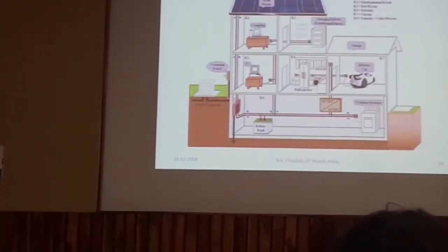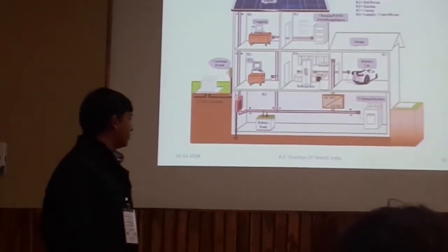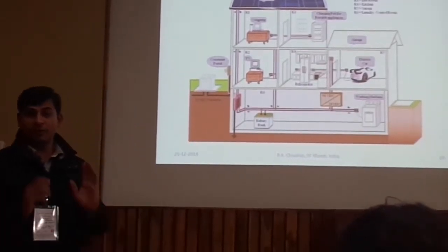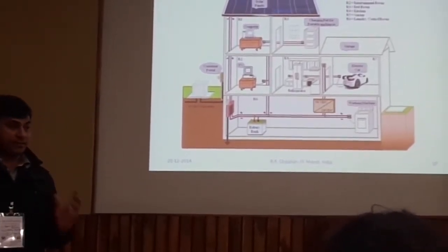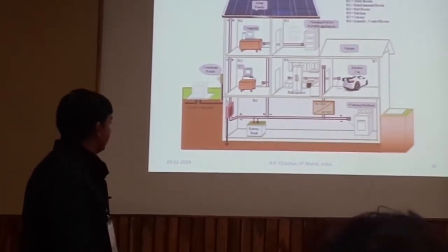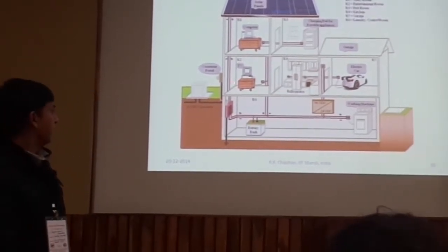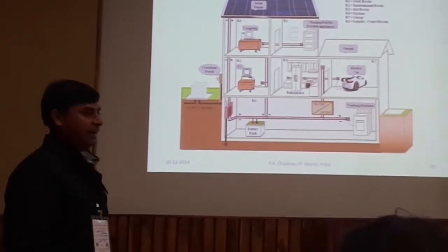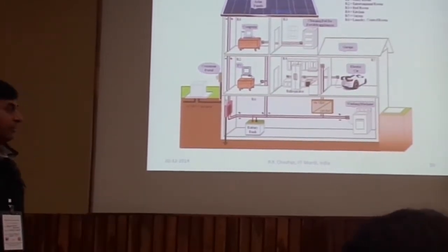So this is the proposed DC distribution system. I have used the unipolar distribution system. Unipolar system means we have a 3-wire system, but I have shown here only 2, positive and negative, and the third one we can see by the white lines. I did not highlight that third wire here.